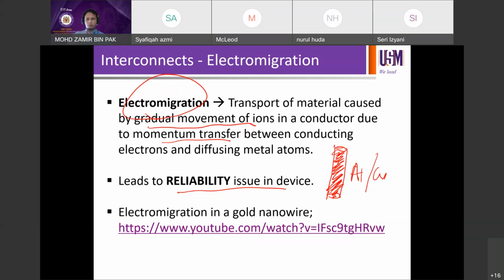Check if there is a failure, then what is it due to? They will do a cross section and send it for investigation, more or less. They're going to do the diagnostic of the failure, and then report. They will report and talk to the main process modules, litho or etch or whatever, a metal deposition, and try to fix the problem, right? So, FA and reliability.